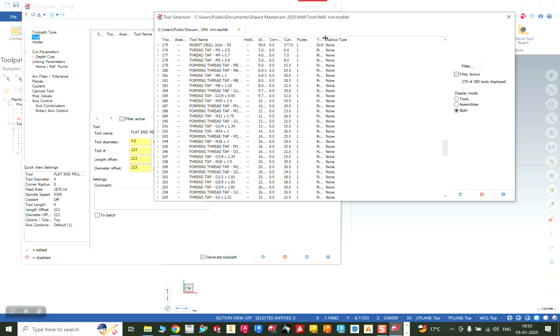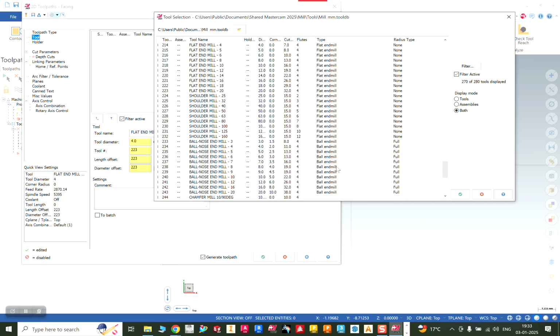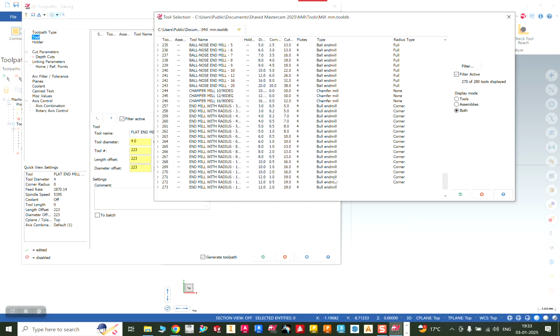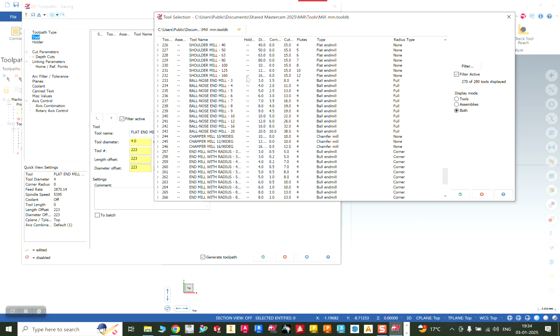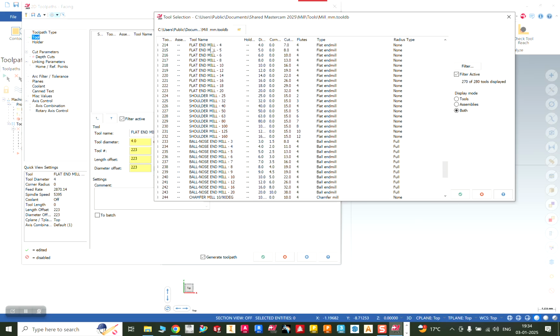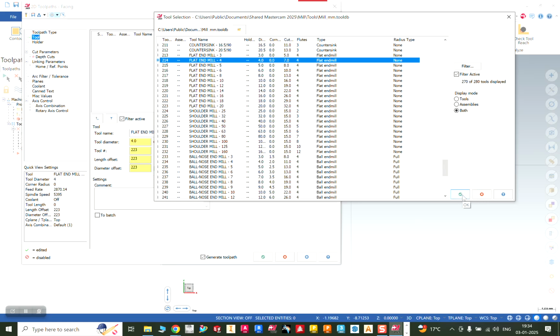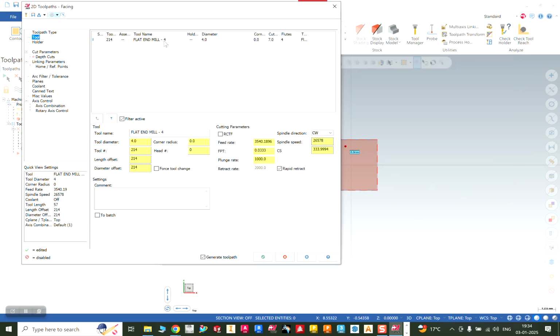You can increase that size, you can see here. These are your flat end mills, and ball end mills for finishing operations. These are round in shape. After that, the specifications or the size you give is going to be very important. Here the sizes are there. If you want to pick the diameter from here, you can pick it from here also. For the 4 mm mill, you can click over here, and you will see that the tool is added over here.